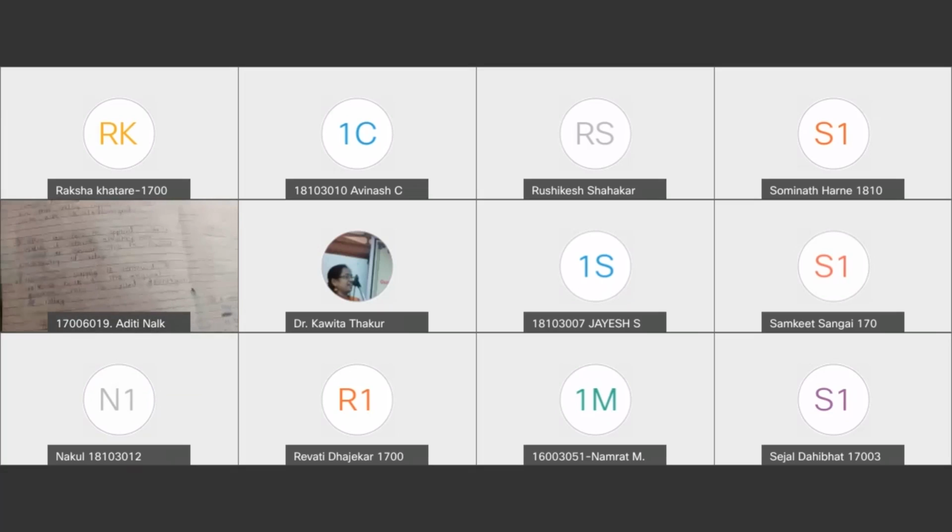To the load. In the relay, the copper coil and the iron core act as an electromagnet. When the coil is applied with a DC current, it starts attracting the contact as shown. This is called the energizing of the relay. And when the supply is removed, it returns to the original position. This is called the de-energizing of the relay.